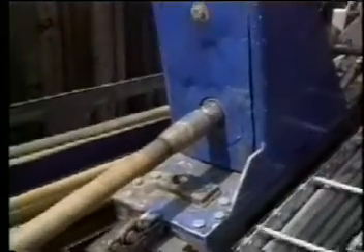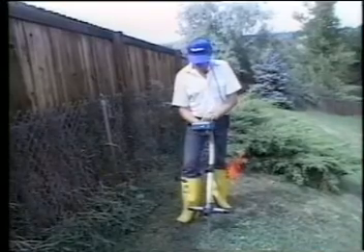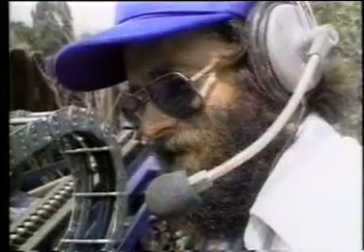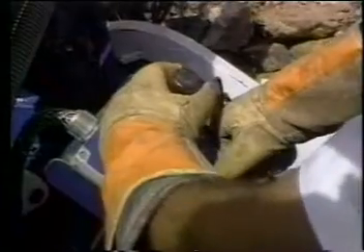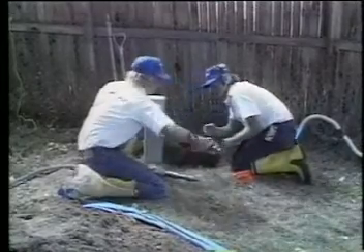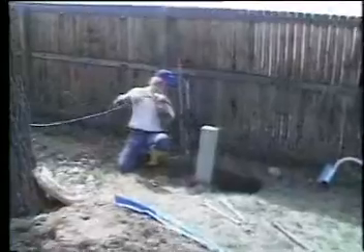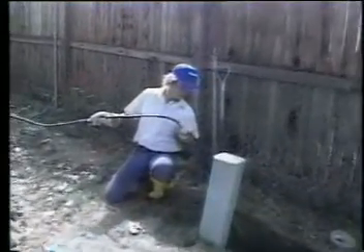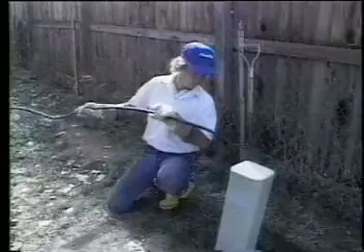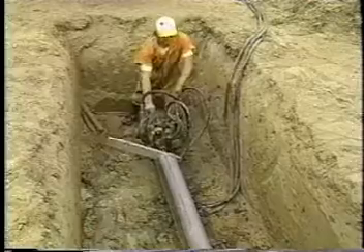The position and depth of the tool are constantly monitored by highly accurate locating electronics. Crew members keep in radio contact to control the depth and direction of the cutting head to keep it on track to avoid obstacles. When the cutting head reaches its target, the steerable head is removed and replaced with a reamer. The cable, duct, or conduit is attached to the reamer using a swivel, and the drill pipe drawn back through the tunnel, completing the operation. For longer spans, larger boring equipment is used to place high-density polyethylene or steel casing through which duct or cable can be pulled.